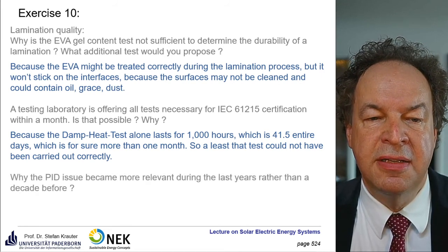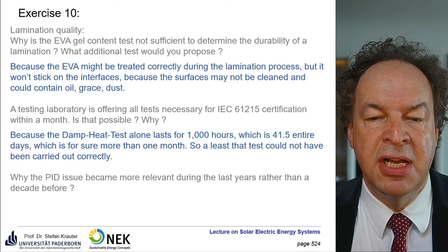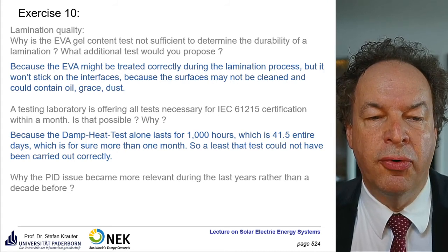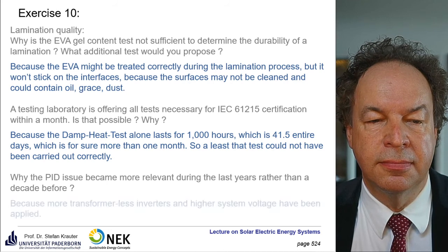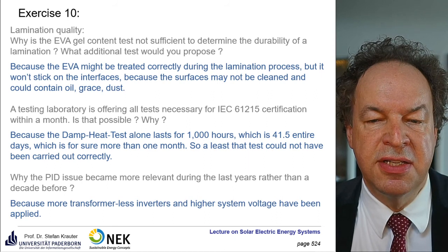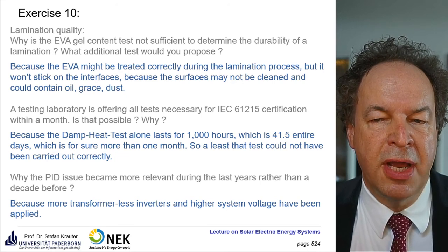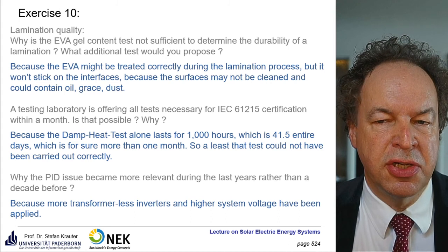Why did the PID issue become more relevant during the last years rather than a decade before? Because more transformerless inverters and higher system voltage have been applied. Also, some decades ago, the operators didn't pay so close attention to the actual yield.